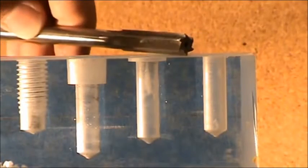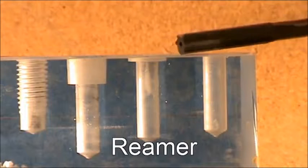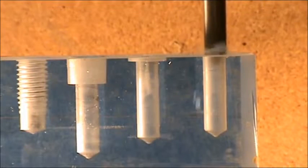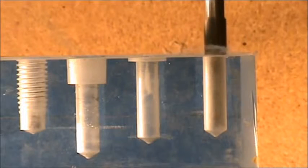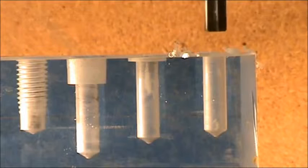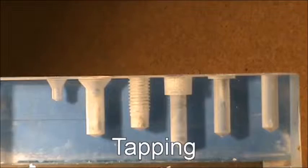Okay, first we will look at reaming. This is the reaming tool, or reamer. When we drill a hole, it's pretty much a roughing operation. Reaming is designed to take off a little bit of the material, but it cleans the hole out.